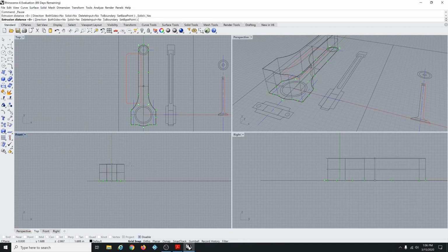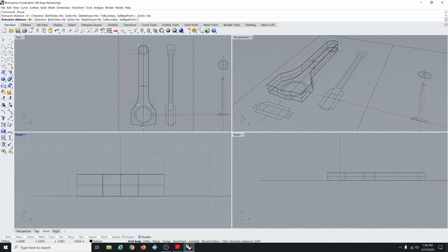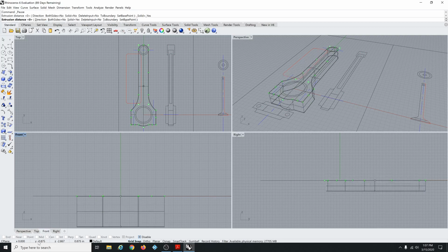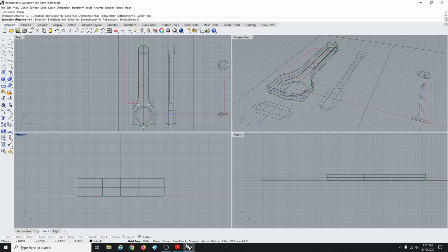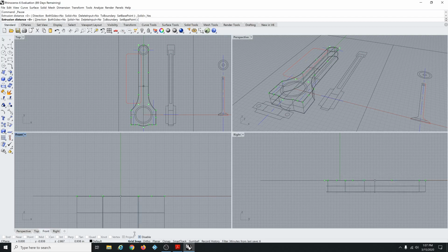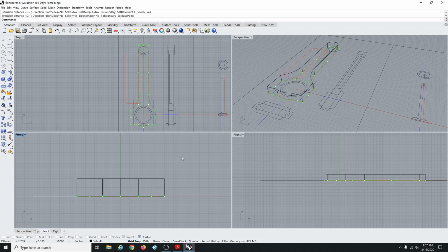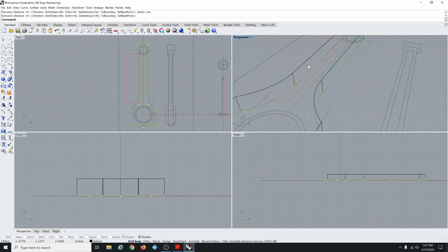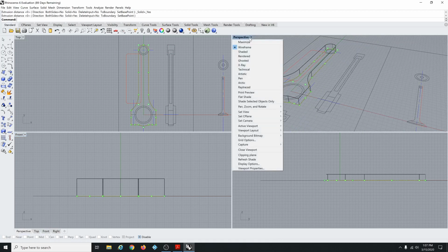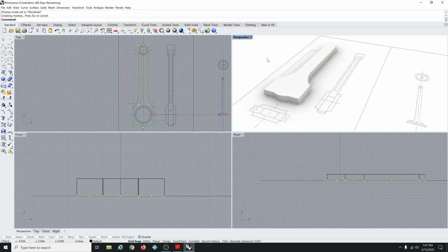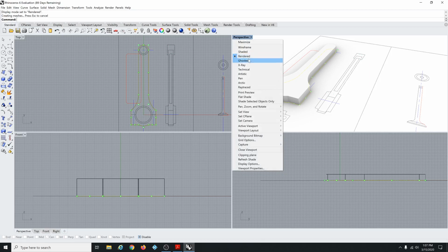And then drop down to the front view, and just using the grid snap and looking at the number at the bottom, the Y value, look at that, and when you see a 1/2 inch with the grid snap on, right? Grid snap is in bold. Click there, and we've extruded it. Now, you can't really tell in the perspective view yet, so we need to change to rendered. So go over here to rendered, or actually ghosted most of the time.